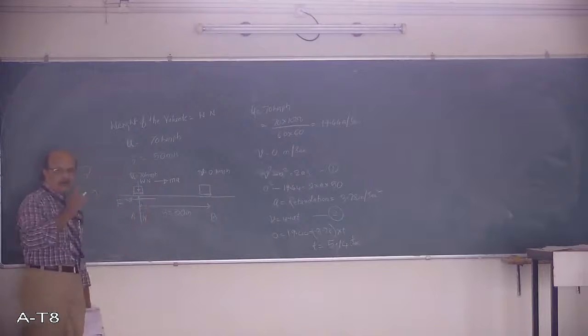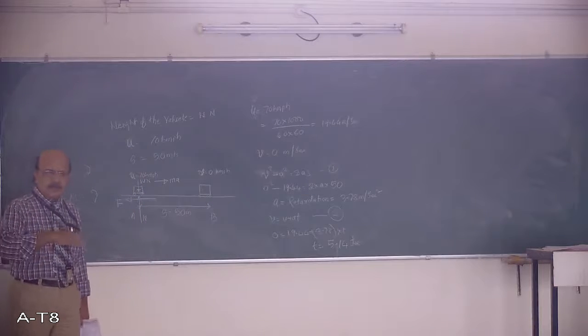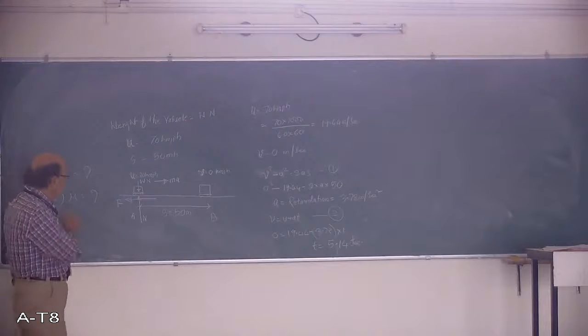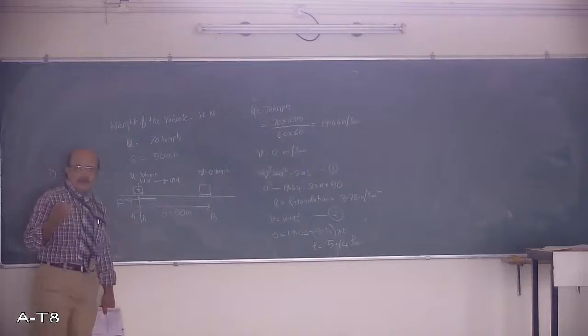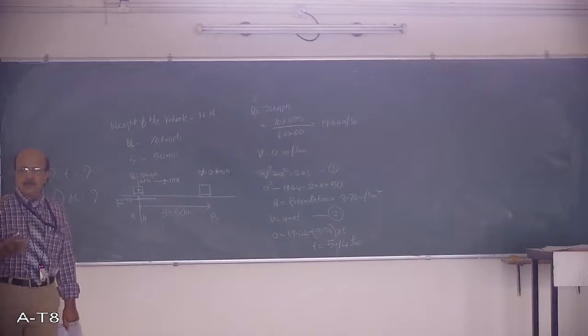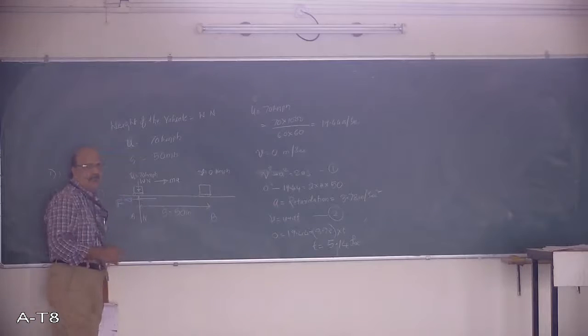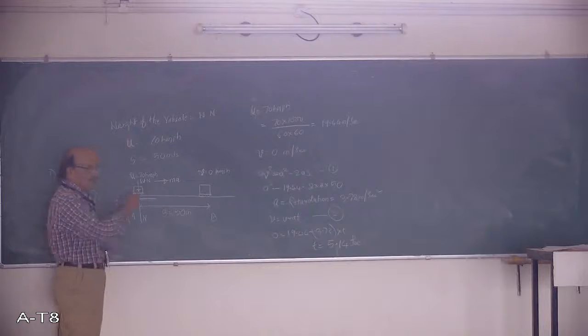That is a little bit confusing, because in other cases you consider, that point will be confusing. In which direction does the inertia force act? Most of the times it is opposite to the direction of the movement, that is one thing. But in this case the vehicle is moving in this direction, but I am taking the inertia force also in the same direction.